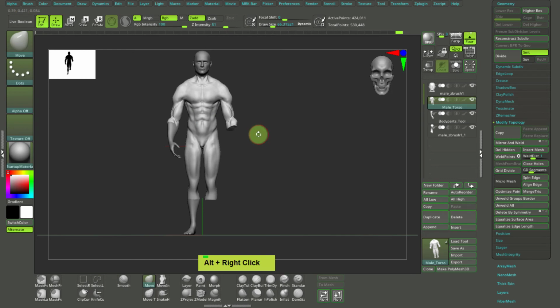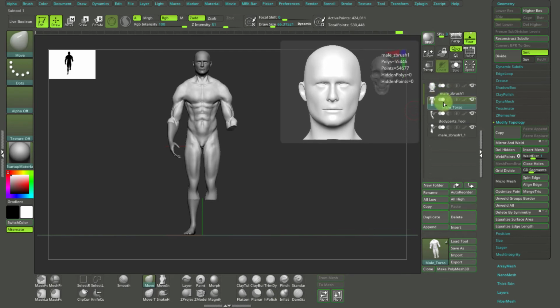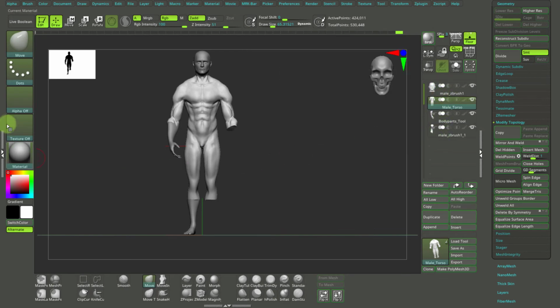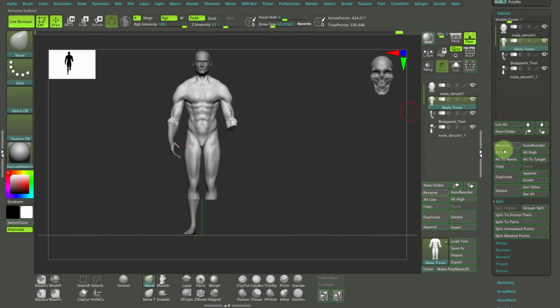It's time to weld. Okay, so right away, because it is set to union, everything's union, we just have to turn on live Boolean. So look for the key, live Boolean. Now it's active, so it will recognize these elements as part of the game. And to actually perform live Boolean, we have to go to Subtool, and in Subtool we have Boolean, and hit Boolean Mesh.